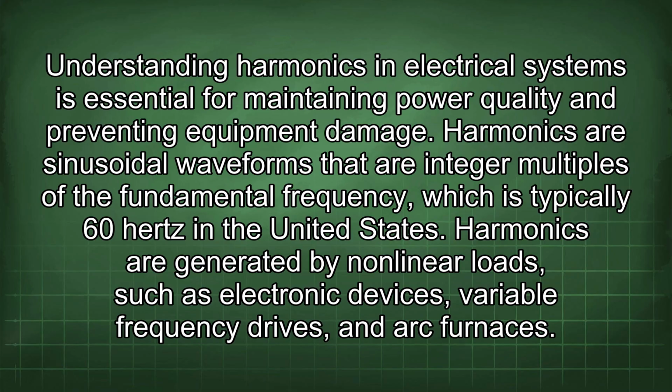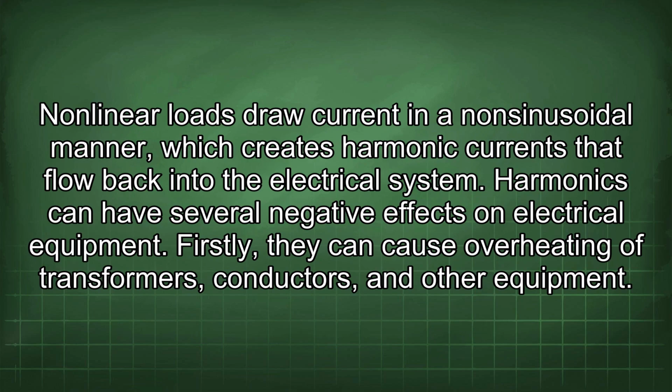Harmonics are sinusoidal waveforms that are integer multiples of the fundamental frequency, which is typically 60 Hz in the United States. Harmonics are generated by nonlinear loads, such as electronic devices, variable frequency drives, and arc furnaces. Nonlinear loads draw current in a non-sinusoidal manner, which creates harmonic currents that flow back into the electrical system.